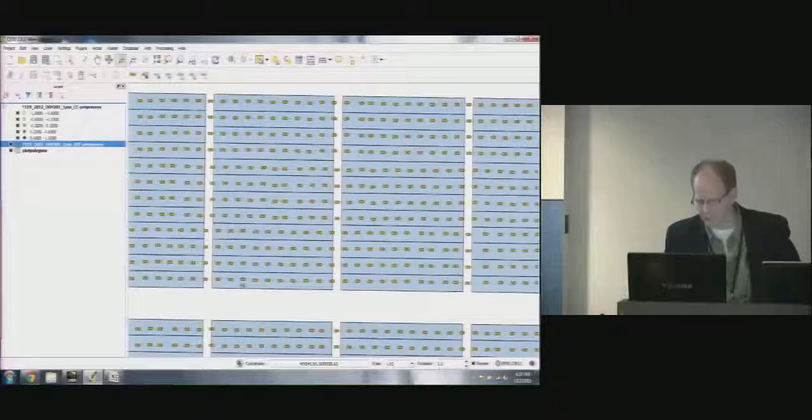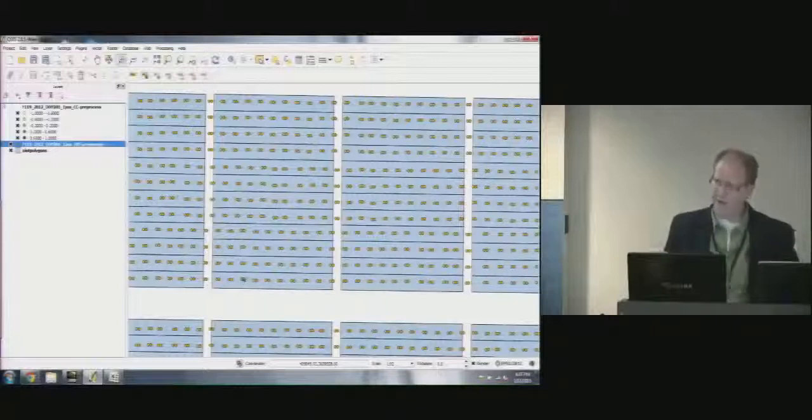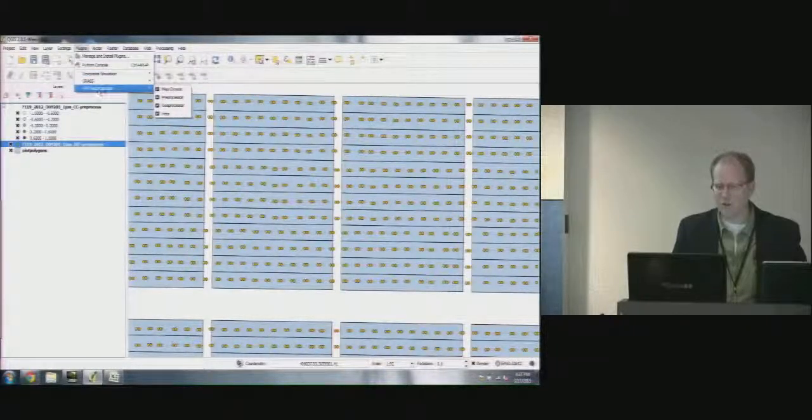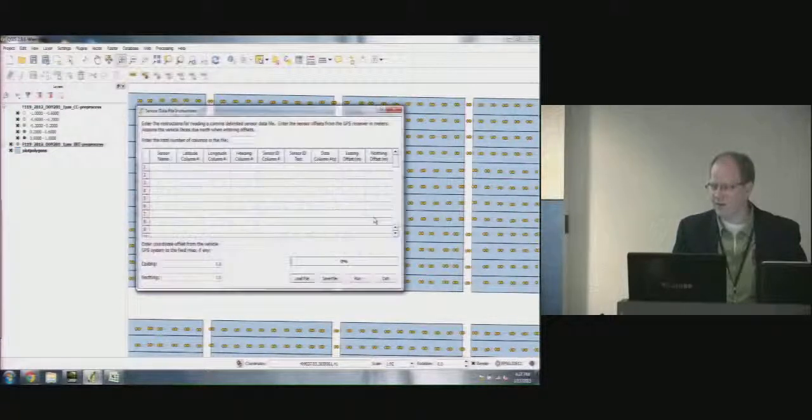Again, whichever one of these sensors is looking forward, the position of the sensor is what's being recorded here, not where the sensor is looking. You have to provide some additional offset to change that, and if you knew what it was, you could do that in the preprocessor here by considering additional easting or northing offsets.